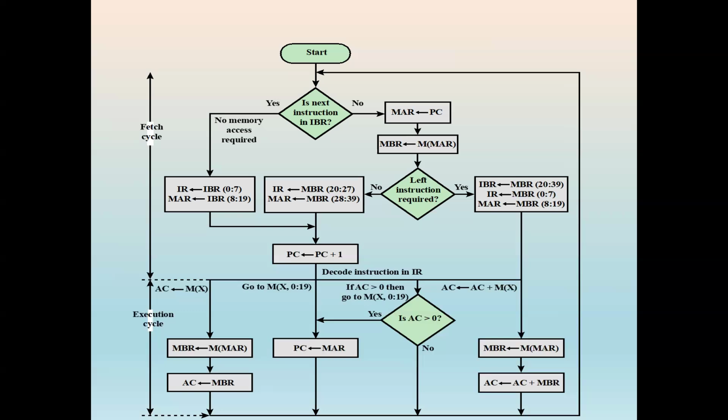Why the indirection? Normally these operations are controlled by electronic circuits and result in the use of that data path. So to simplify the electronics, there's only one register that is used to specify the address in memory for a read or write, and only one register is used for the source and destination.